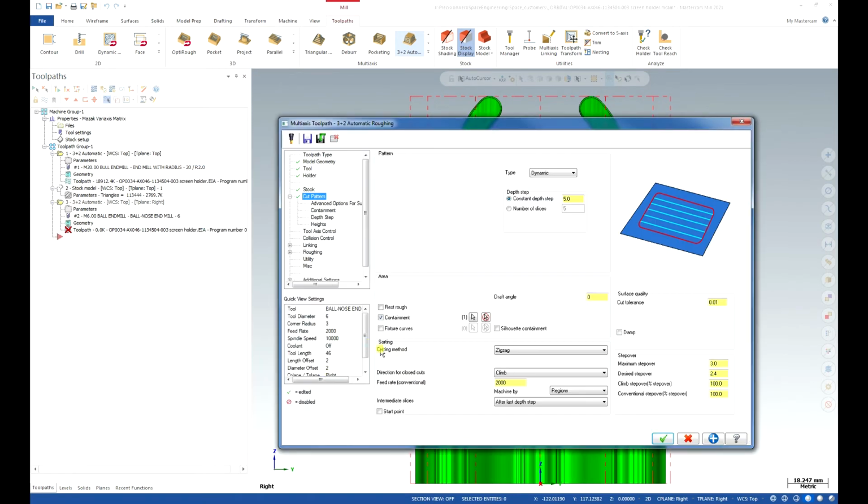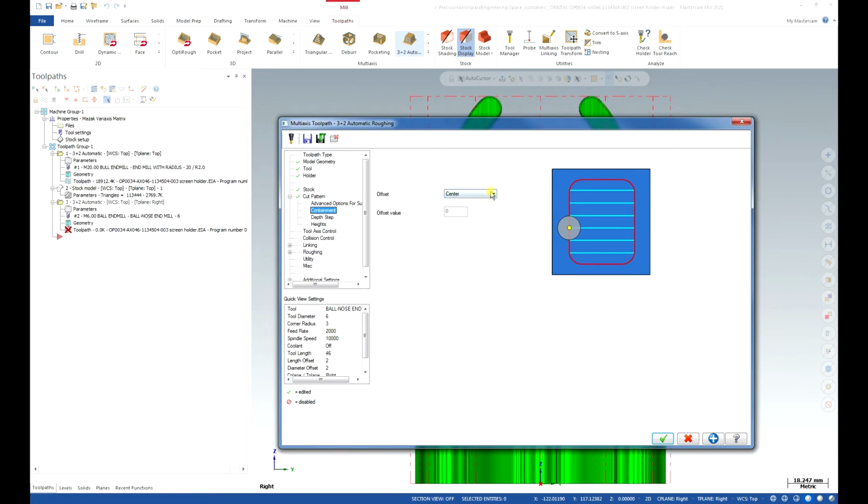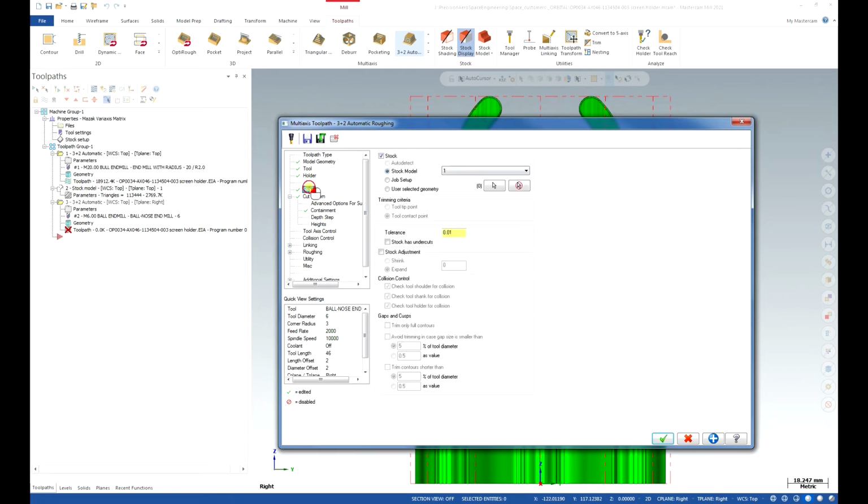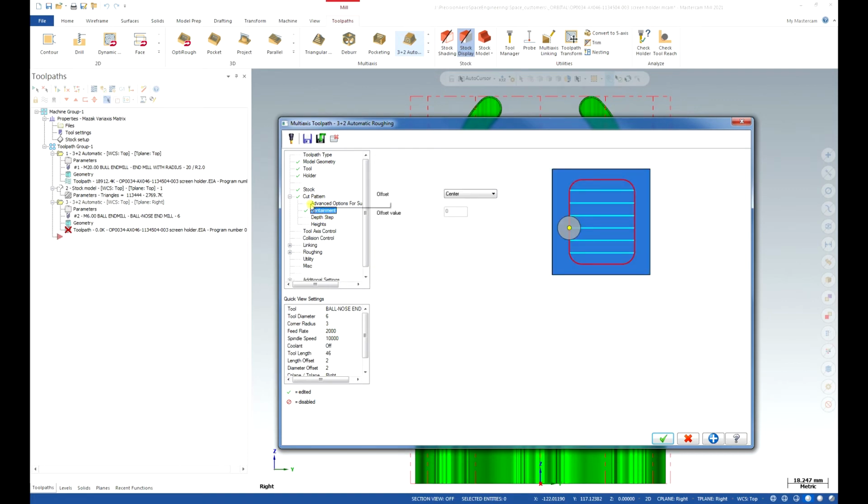Now you can see that you have one chain with the containment, and after adding the chain, you activate one of the sub pages, and you have 3 standard options for controlling the containment of the tool's motion during machining. You can keep the tool inside the boundary, you can keep it on the center line or outside. Plus you have an offset that you can set. In our case, we can keep it on the center or outside because we have our stock model selected and we will cut out all the air cuts anyway.